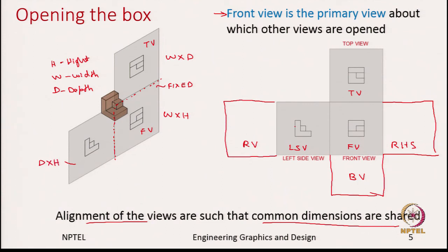So, now let us focus on front and the top view. What is common between them? Both of them capture the width, and you look at the placement of the front view and the top view. So, for example, if I extend these lines, they are all aligned.